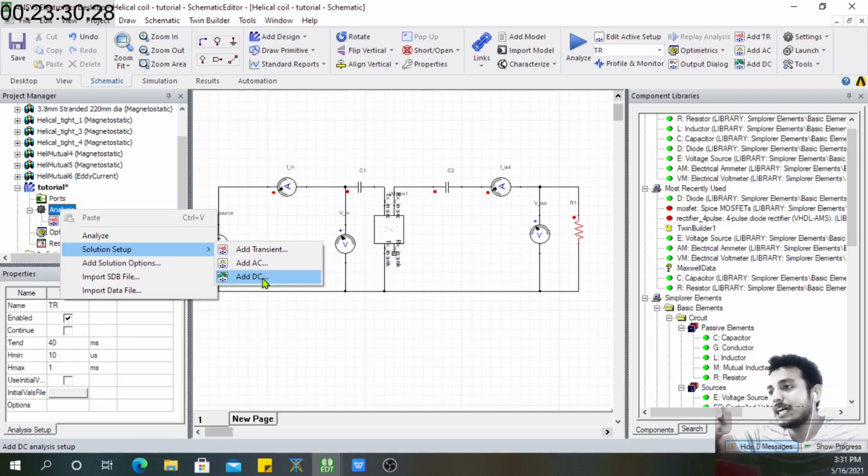That's the only knob that we can rotate to bring that resonance to this particular frequency, and that we do by using the resonance formula, as simple as that, omega L equals 1 upon omega C, and whatever we get from there, the value of C, for now we got that as we calculated from Excel.